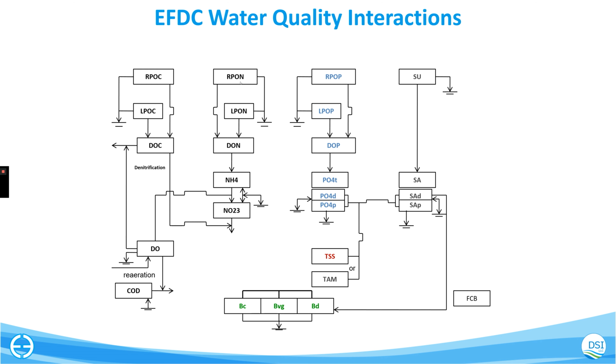That said, this is where I was coming to on this COD value down here. If all you have is BOD and you're only interested in BOD and DO, like a typical stream with a wastewater treatment plant loading into it, you can build a really simple DO model, like a Streeter-Phelps model.